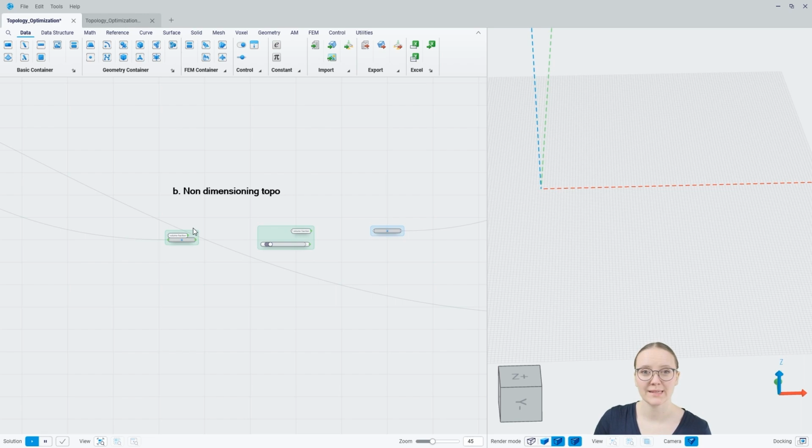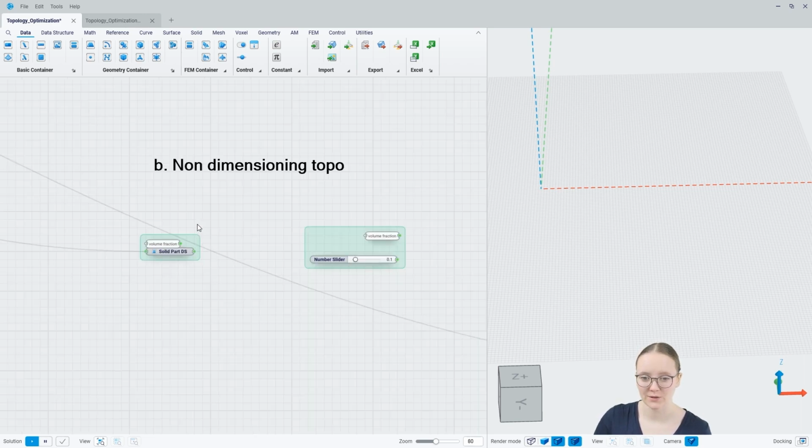This topology optimization is stiffness based using the volume fraction response, and you will get very discrete load paths. However, you will need further processing because these are not dimensioned yet. So this constraint is ideal for a reconstruction process using the skeleton process. If you define those lines, these discrete lines, you get a rod-shaped result, but then you have to do a cross-section optimization to actually get the ideal result for the stress.